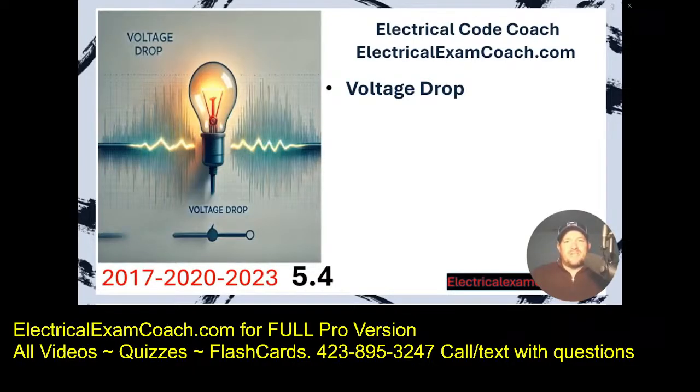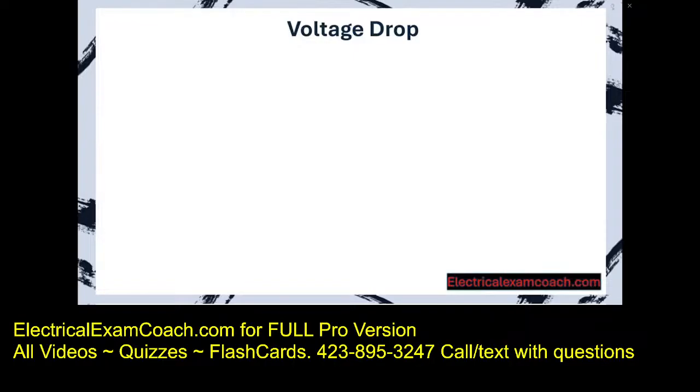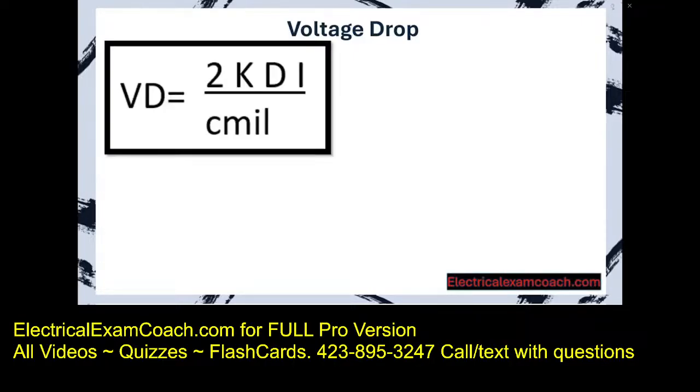Let's get to it. If you were to do an internet search for a voltage drop formula, you would likely find this one right here: voltage drop equals 2 K D I over C mil. And that is an excellent formula, and it's actually the one that I use. But I've rearranged it so it's easier to remember.